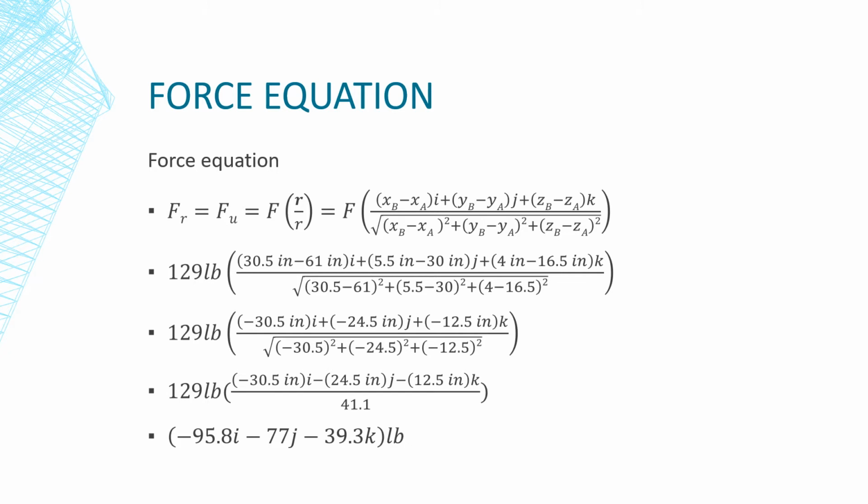Plugging in everything, the force is 129 pounds times (30.5 inches minus 61 inches)i plus (5.5 inches minus 30 inches)j plus (4 inches minus 16.5 inches)k, all over the square root of (30.5 minus 61) squared plus (5.5 minus 30) squared plus (4 minus 16.5) squared.